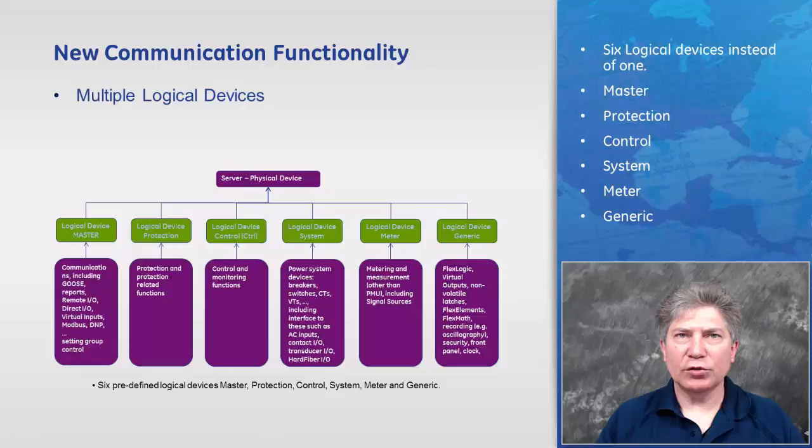There are 6 logical devices now: master, protection, control, system, metering, and general. The master contains the communications including Goose, reports, remote I/O, direct I/O, virtual inputs, Modbus, DNP, and so on. The protection controls just that, all the protection functions. The control contains control and monitoring functions.